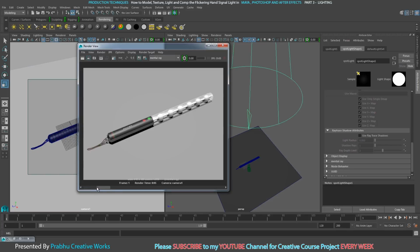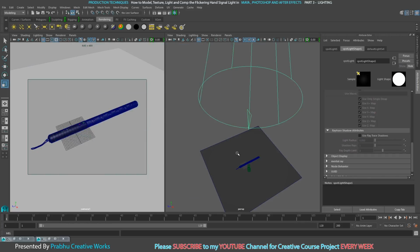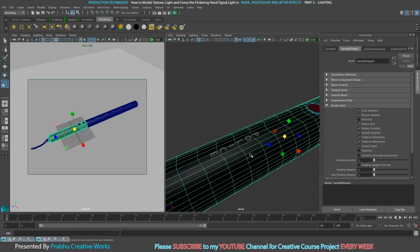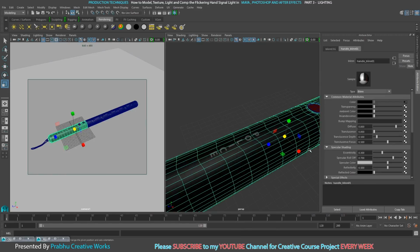So now I want to reduce the specular color and reflectivity of this object over here in the handle. So go close over here, then click this object, right click and choose material attributes. That means you go directly to the material. So now I want to reduce the specular color for this object. I reduce my reflectivity to 0.3.